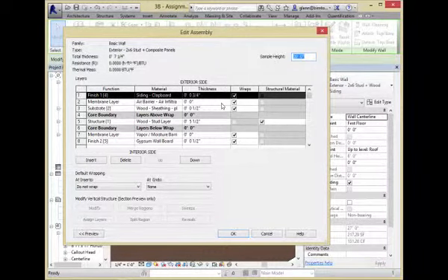So this wall, and this is the way I set them all up: the wood frame layer being 5.5, the gypsum wall board. The truth is it's the same in all those wall types. I didn't change any of that. All I really changed was the notion of what the finished material is. So if you want to have about the same wall and just change the finished material, start with one of my walls and change it to a different finished material. And here's how you do that.